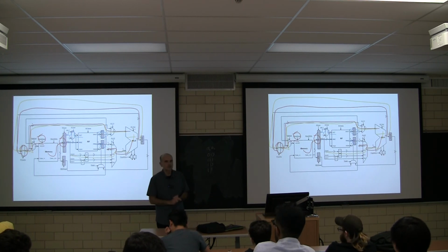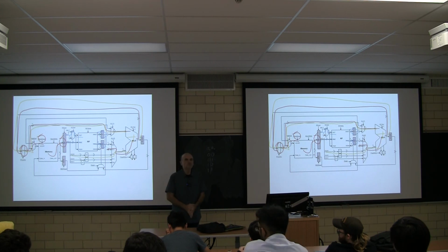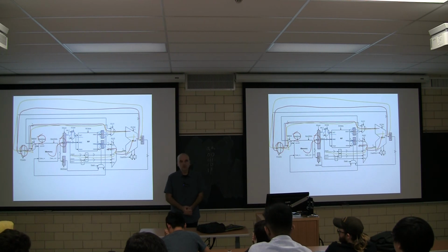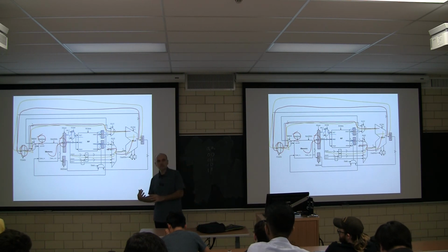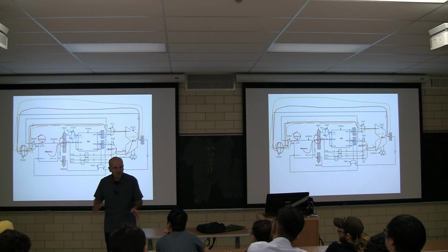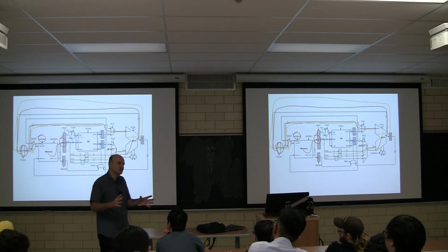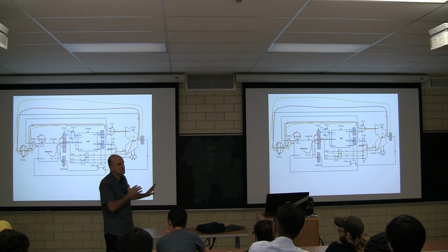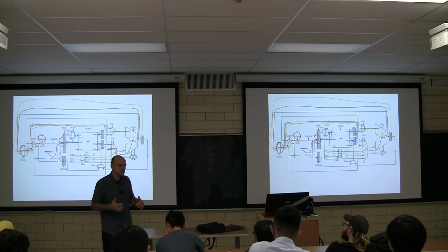So when you compile the code, the compiler calculates the offset from that point in the program to where you want to go in the program, and then puts that number in the instruction. This is a piece of hardware that says there's an instruction somewhere in memory that tells me what to do. Who put that instruction there? How much effort they had to do that? This machine doesn't care. Right now, we're the hardware designers.